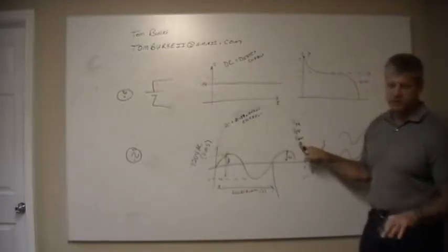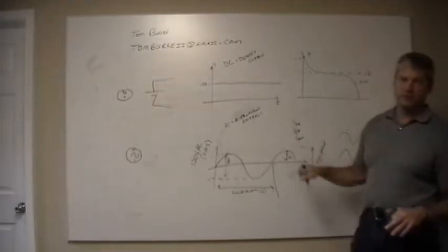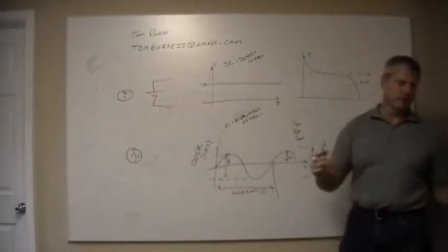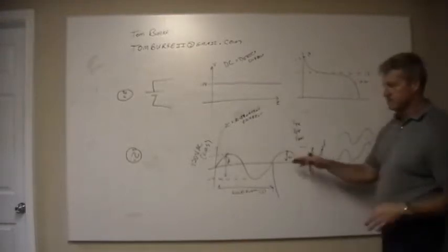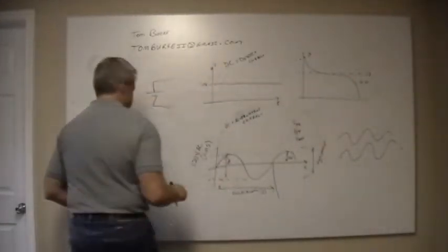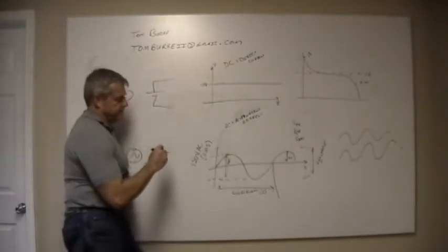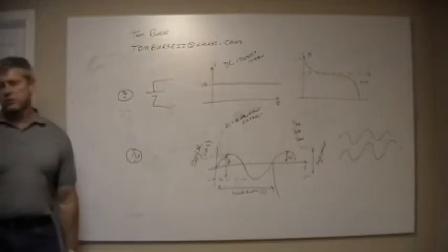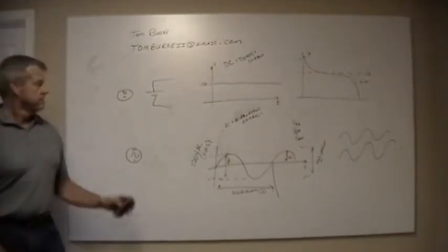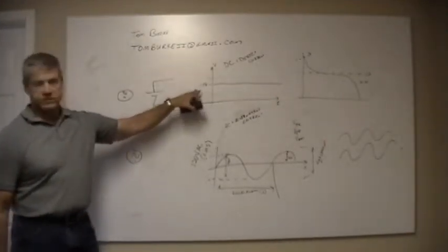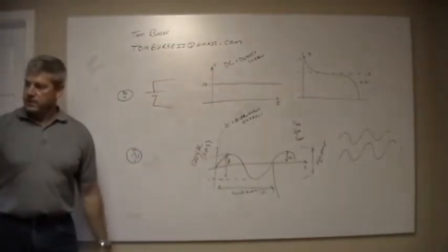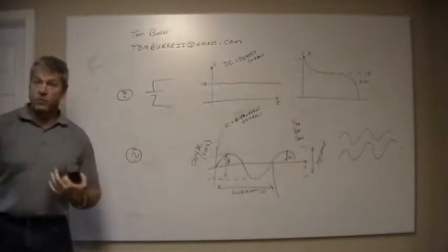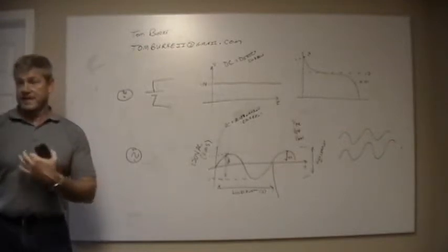And you have your V RMS, which generally only works well for sinusoidal waveforms. You can work your way and do the math and get the RMS for square waves, triangle waves, anything else, but it's easiest for this. The 120 volts RMS is the equivalent DC value of that. So if I were to have a 120 volt DC source, it would be the equivalent energy, power, whatever you want to put it, coming out of the wall as that 120 volt AC source.